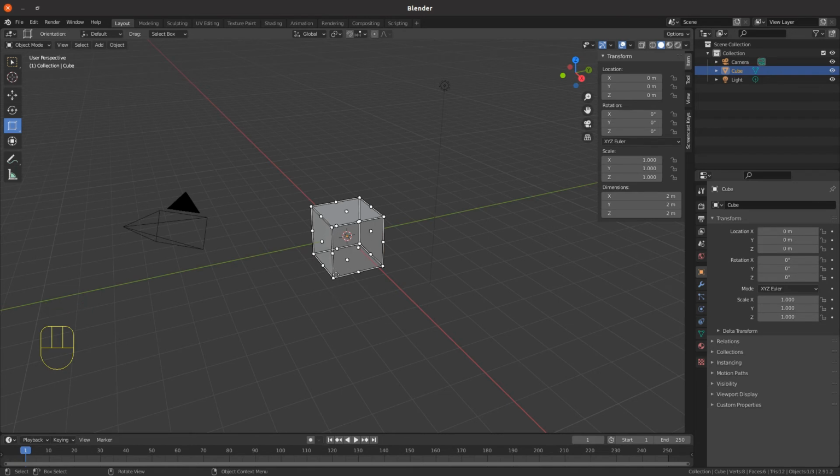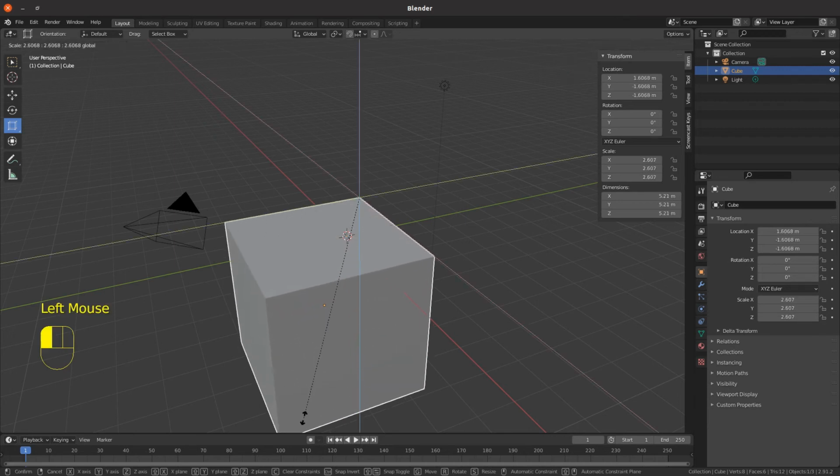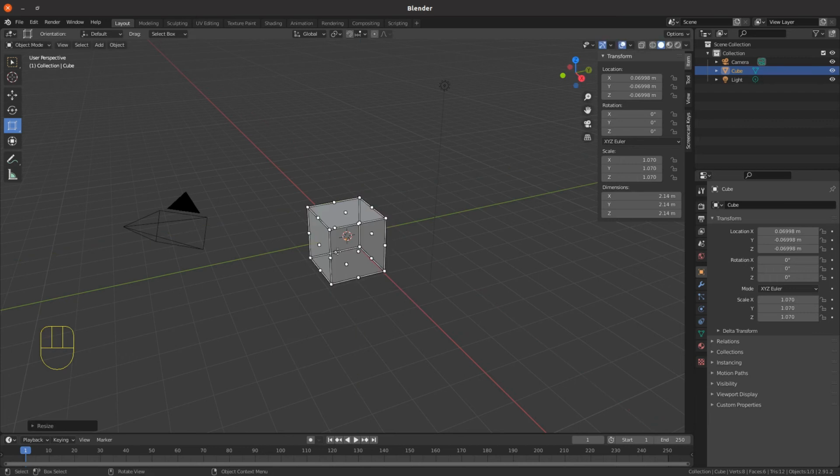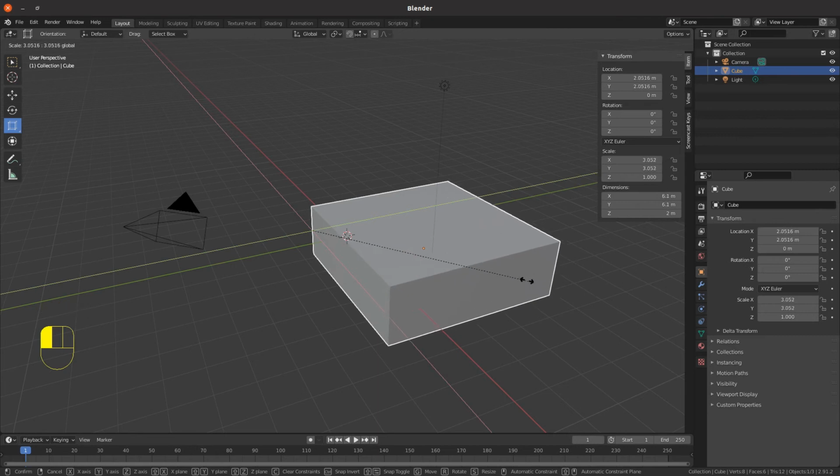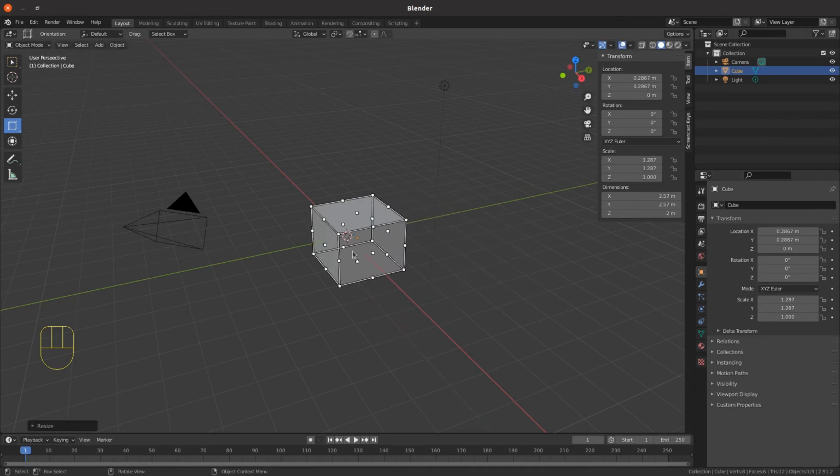And you can drag out the corner markers to increase it. That means it's moving from its furthest point from the corner marker. And these sidebars will drag it out from the corner. So it gives you a different option to scale. You're not constrained to scaling from the centre point with the scale cage.